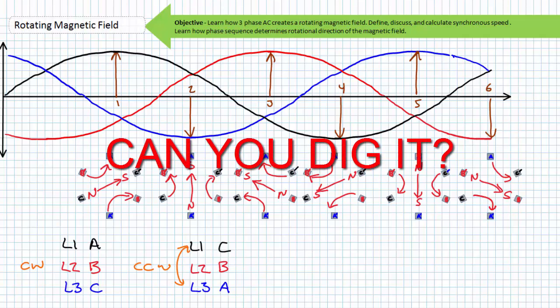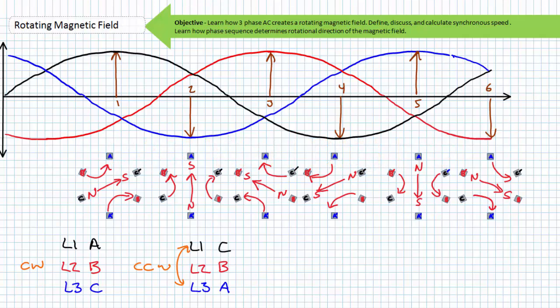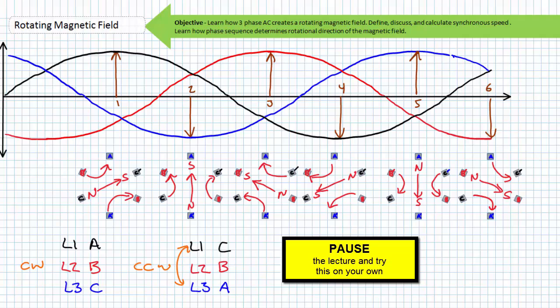Can you dig it? Simply by interchanging any two leads, we were capable of reversing the direction of the rotating magnetic field. If you need to, by all means, pause the lecture and take some time to let this soak in.